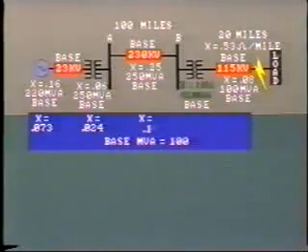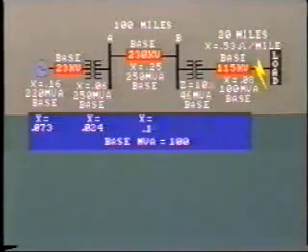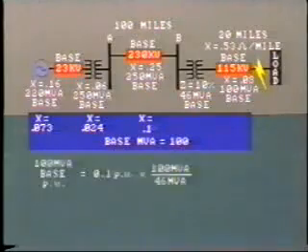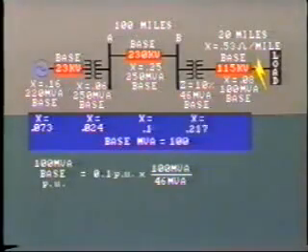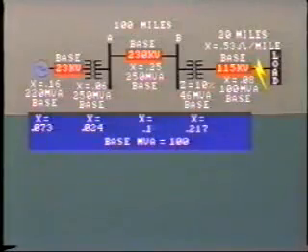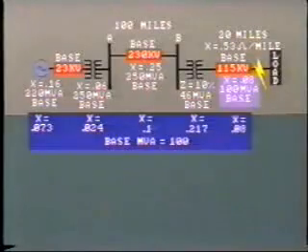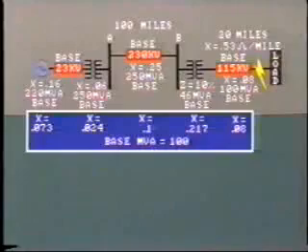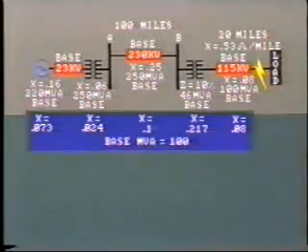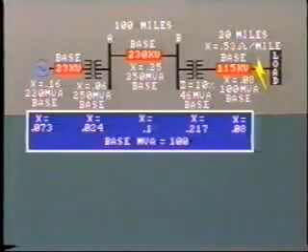We already know the impedance, let's call it reactance value for this transformer, 10% at 46 MVA. That is 0.217 per unit on a base of 100 MVA. The 115 kV line we already calculated as 0.08 on a 100 MVA base. So, what do we do now with all of these 100 MVA base values of reactance?